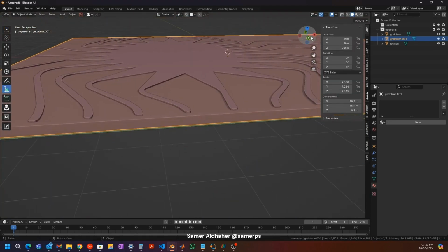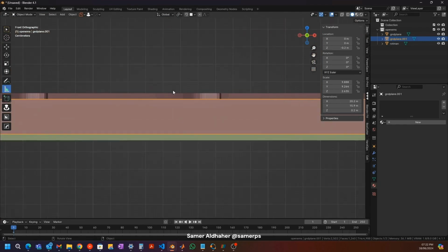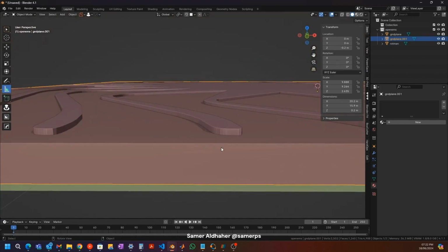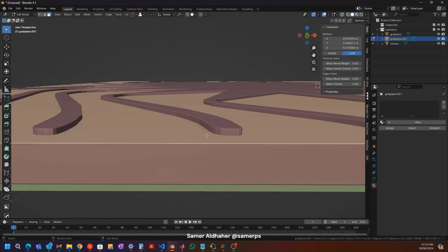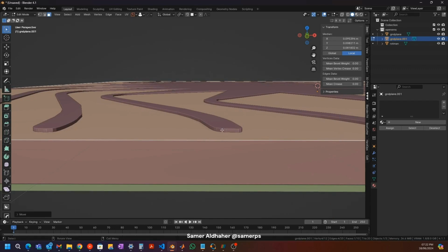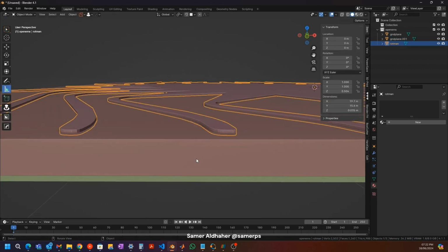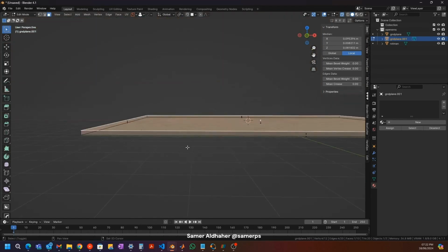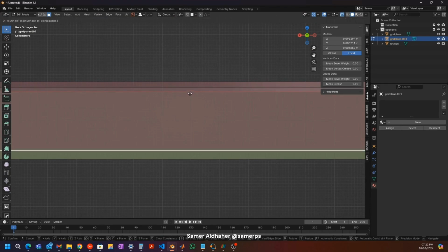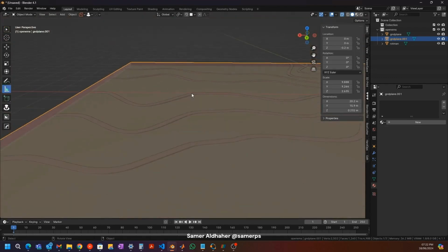Now, one thing in openEMS is that although you can see the substrate and the copper sitting exactly on top of each other, they're snapped to each other. Sometimes I prefer to have a bit of overlap, because that makes the meshing easier. And of course we can change the priorities in openEMS such that we give priority to the copper over the substrate. So let's bring in X-ray mode, and that's the one here. Go back and let's bring this down. So there's a bit of overlap.